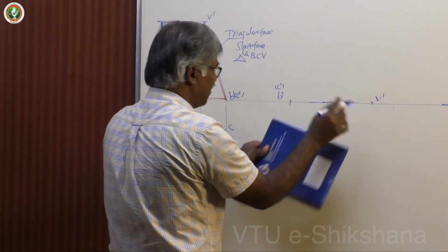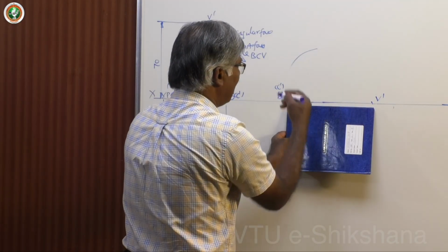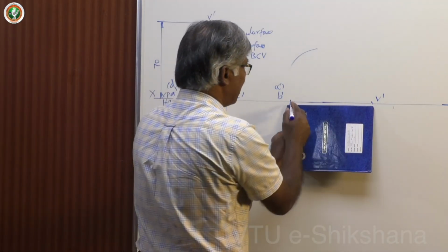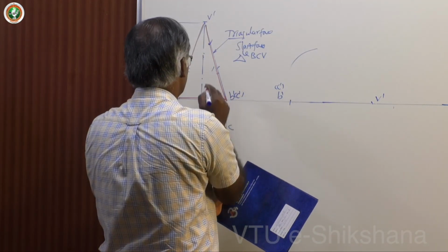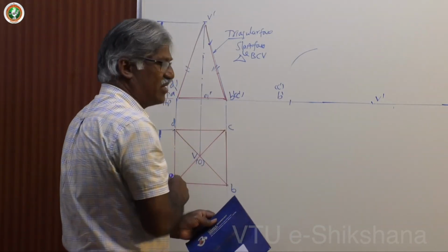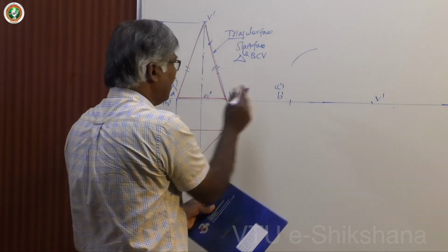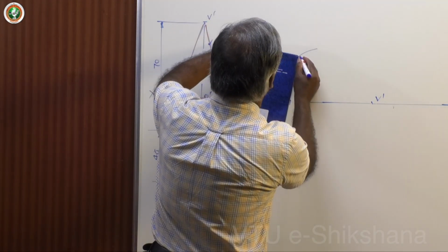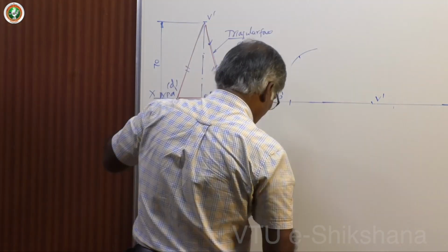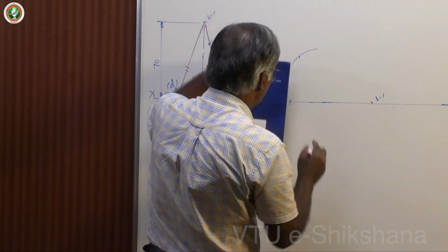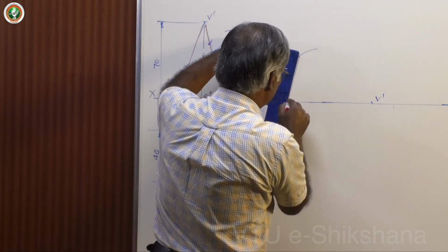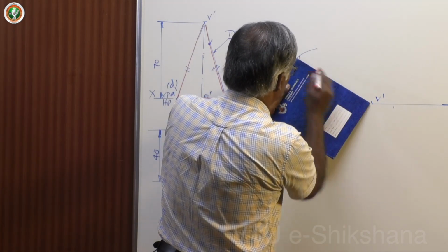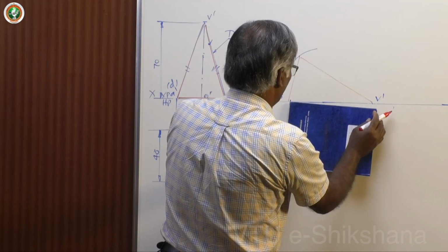With the same distance you draw one more arc with the same radius, because these two are equal, symmetrical because of the symmetry. Then take the base length and cut an arc, that is all. With this base length draw an arc, then you get the second figure, front view, ready. That is all you have to do.